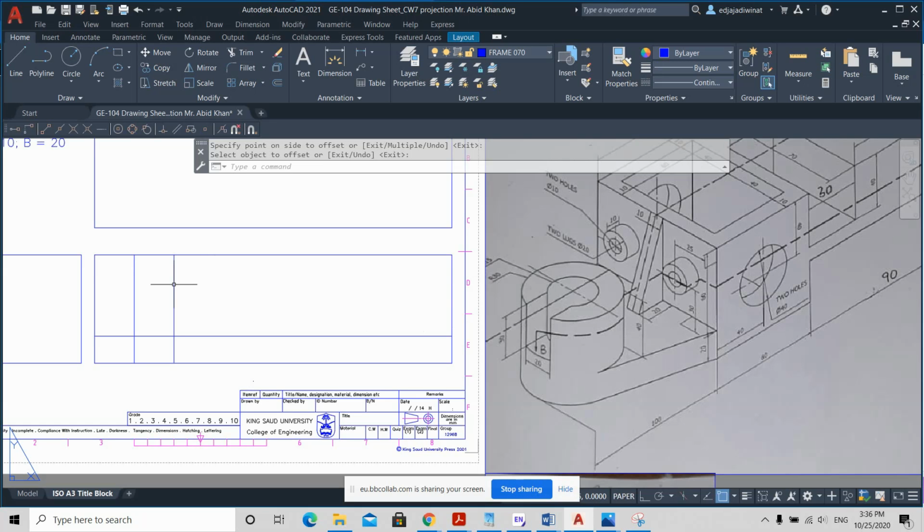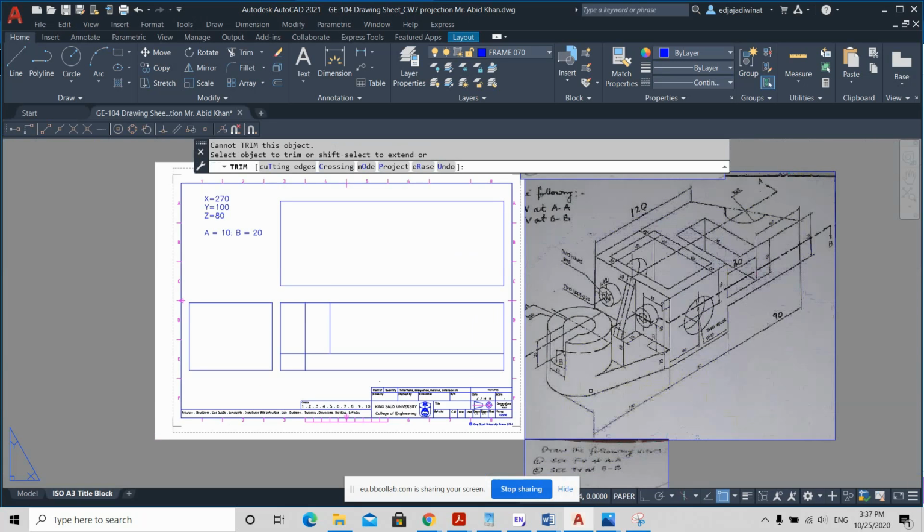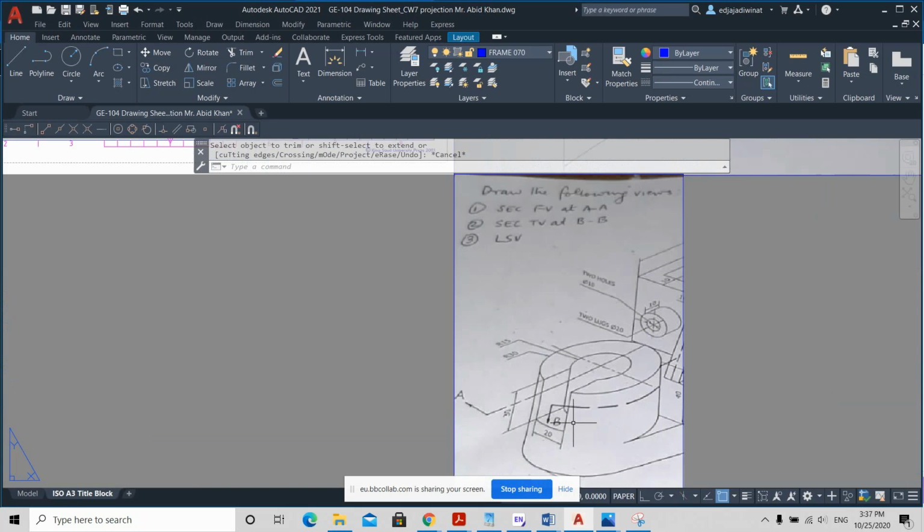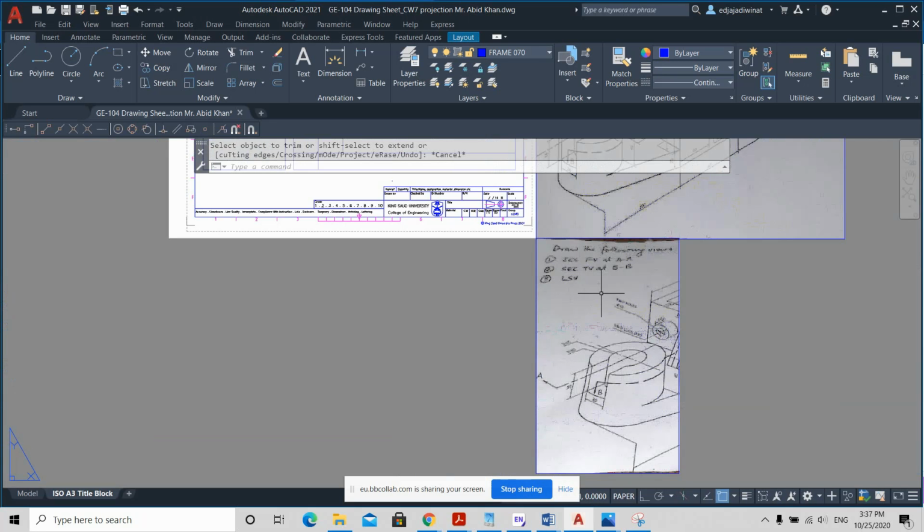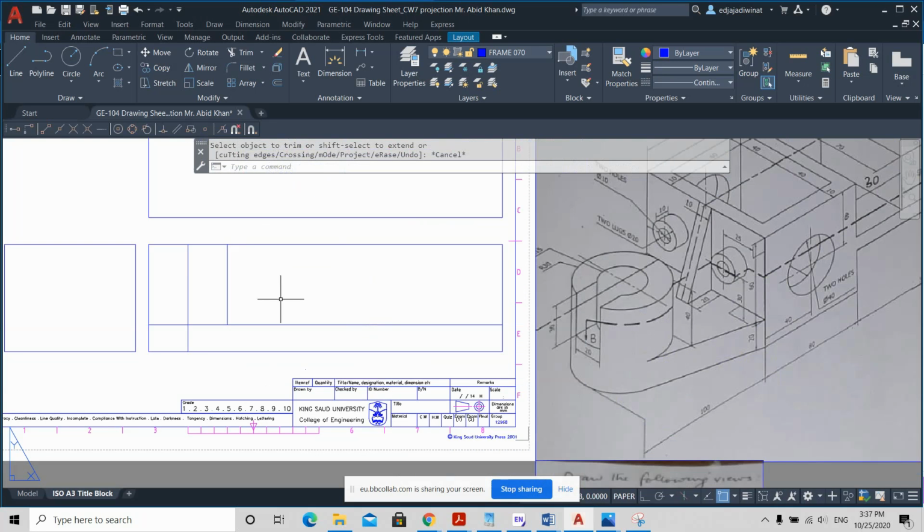And now you have already this cylindrical shape here. You can trim this. Okay, so just to make sure that we realize that this point is that edge here on the right, but at the bottom. And this will be a through hole because it's not informed. Let me check if it is informed or not. Okay, it's not informed regarding the depth. That means it is a through hole, right? It is a through hole.